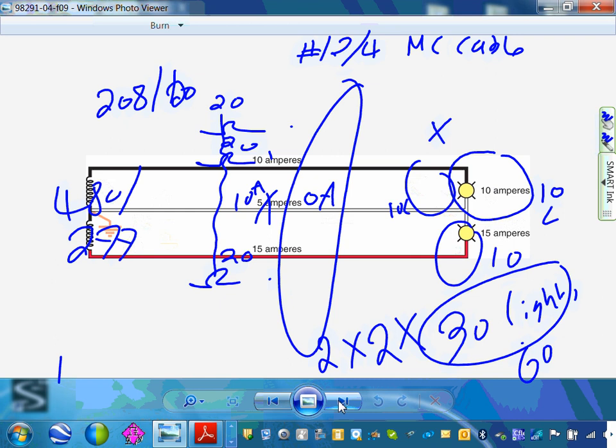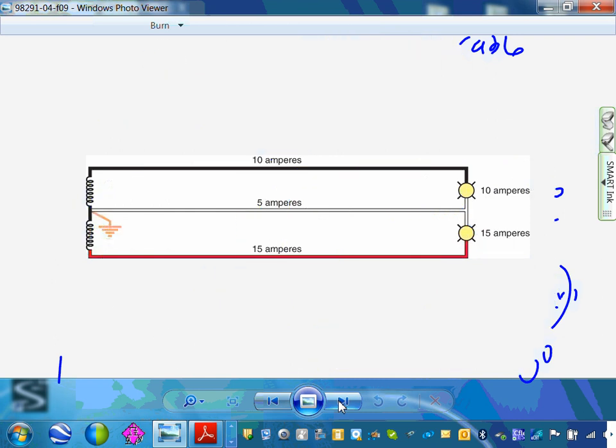This is your single-phase system, guys. You're familiar with that system. This is for the dwelling only. We don't use that one. Also, multi-wire branch circuits, 10 amp, 10 amp. Look at the neutral. The neutral will carry the difference between these two, right? In a single-phase circuit.